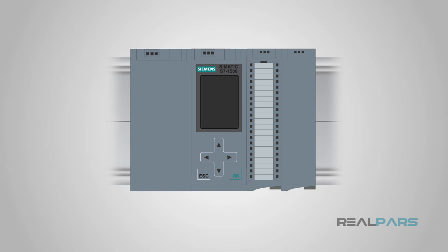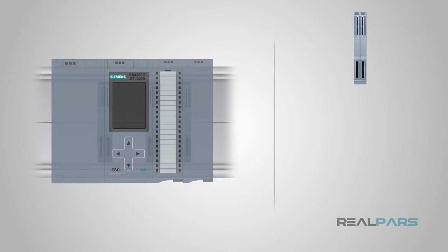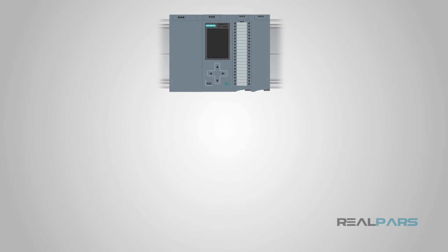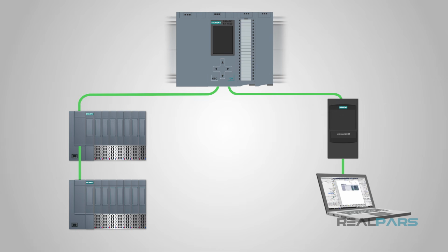The S7-1500 significantly increases performance over the S7-300 with a faster backplane bus, standard Profinet interface, and shorter reaction times. As a result, the updated Profinet interface provides greater reproducibility and precision in the microsecond timeframe. When programming for slower processes, this may not make a noticeable difference in the real world. However, it can be very useful in high-speed applications, such as assembly lines.